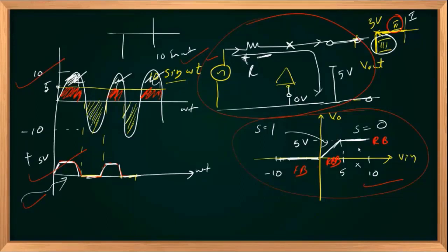We are opening the diode first, then we are identifying the different modes, then we are replacing the diode accordingly, either short, open, or with a voltage source. You should be careful while drawing the voltage source. Cathode is positive, then anode with a VZ value. VZ is the reverse breakdown voltage, VBR or VZ. So this is called a shunt clipper because the diode was present in parallel with output, and you have 2 different slopes, S0 here, S0 here, and S equal to 1 in the linear region.